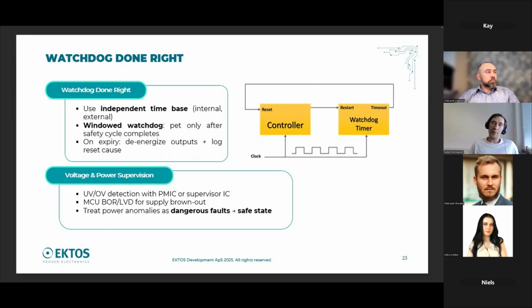And implement the software in a way that some special component will take care of the watchdog and monitor, like a scheduler, that all tasks or all functions in your main are executed in the right way and maybe at the right time. Only if everything is executed correctly, feed the watchdog with a pulse to say that everything is okay.